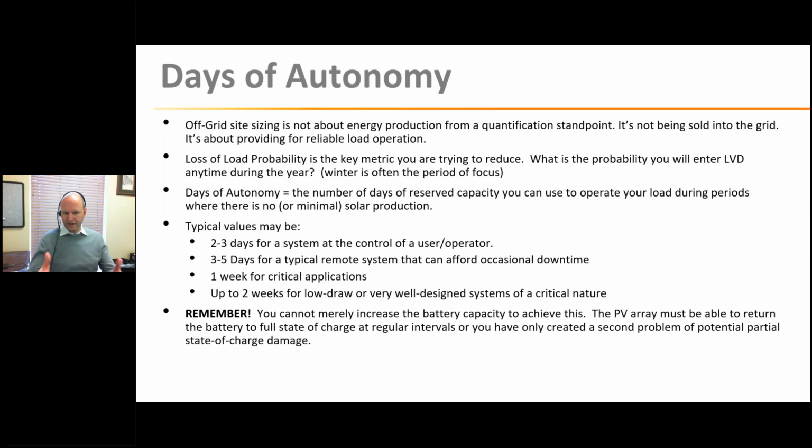So, not every day is sunny. There's days of rain, sometimes multiple days. You have shorter days during the winter. How many days can that battery provide autonomy for the load given how you've sized it? Okay, and this is an important factor.